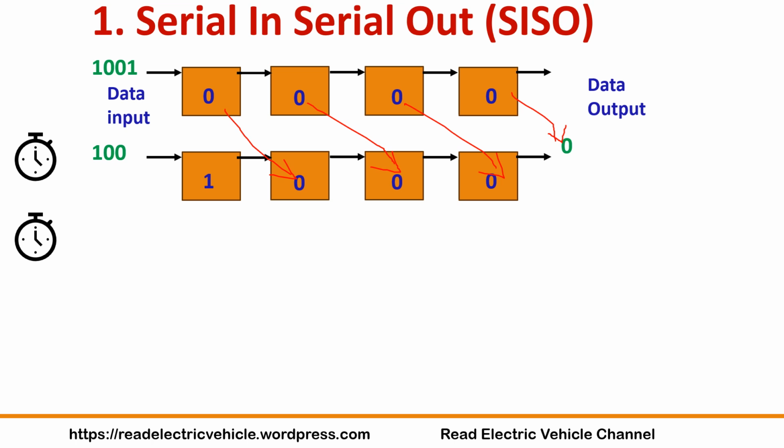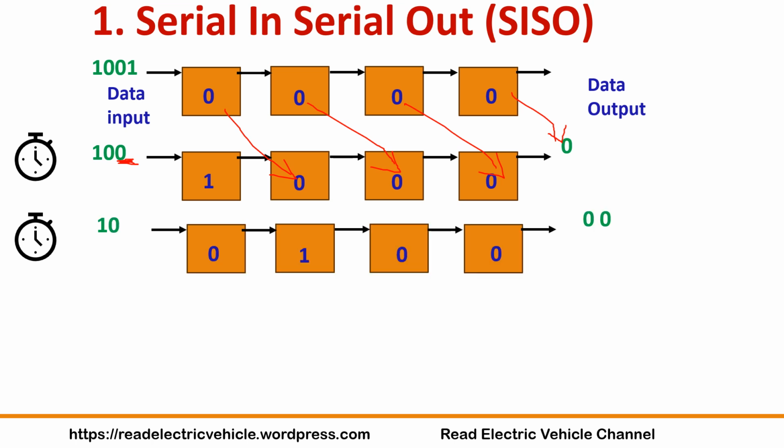So you are giving the second clock pulse. Now what should happen? This is the input data for the flip-flop, so this 0 should enter here. This 0 will come here, whatever was here will come here, and whatever was stored previously here should come out here.